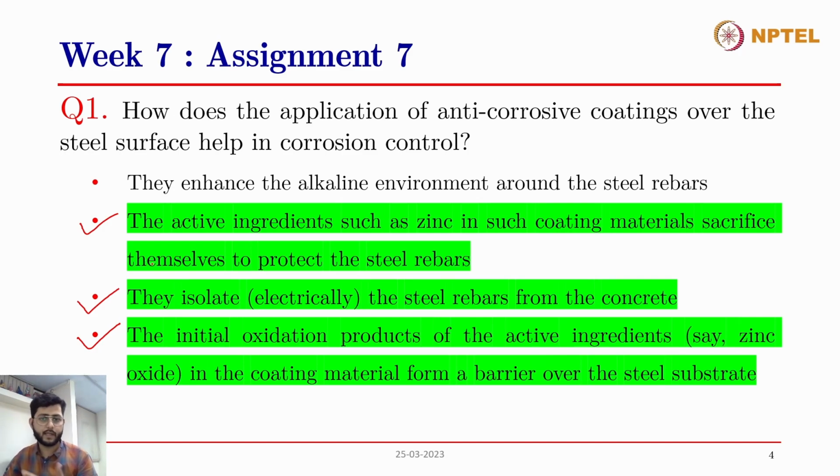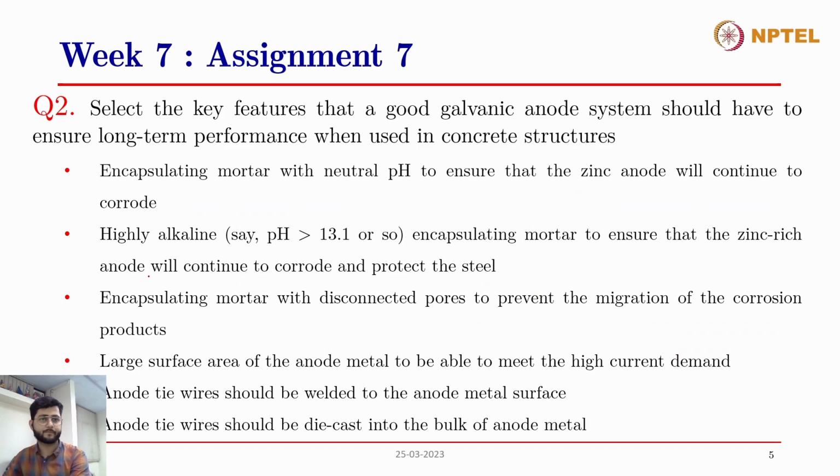But they don't enhance the alkaline environment. They won't, like we have studied in the case of the electrochemical realkalization process, or in other processes as well, when there is deposition of hydroxyl ions around the steel reinforcement, and thereby it regains the passivating film around the steel reinforcement. That won't occur in the case of anti-corrosive coatings. So these three are the correct options. All right.